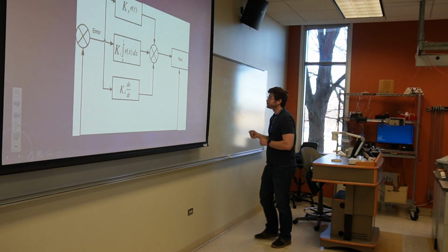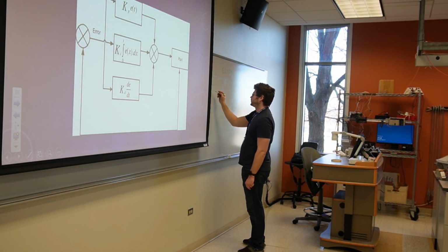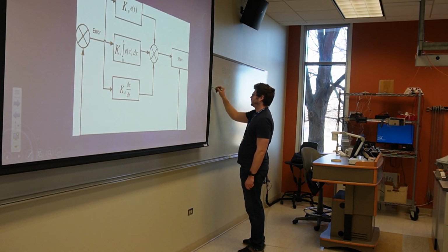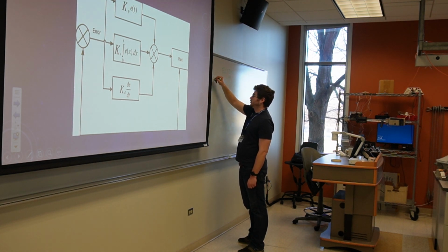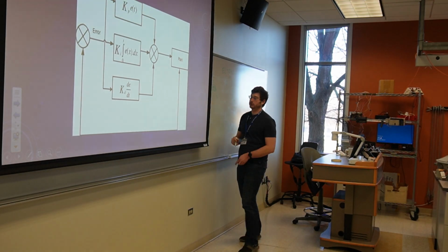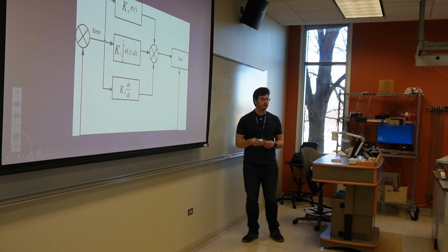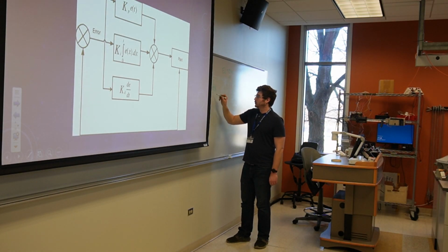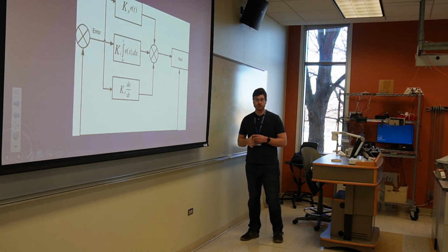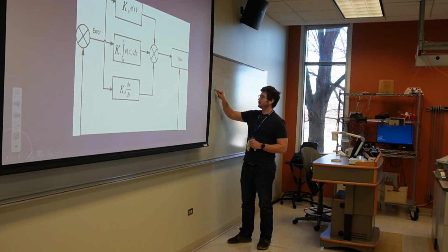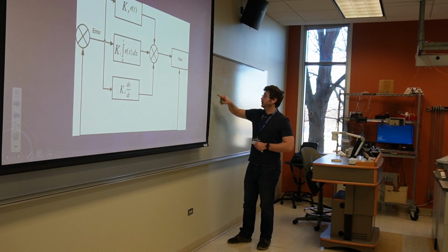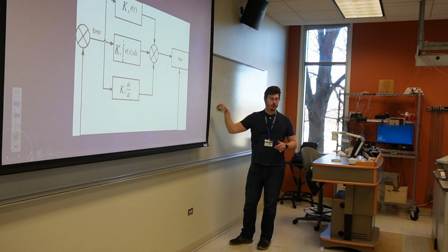So if you buy a little temperature controller box off of Amazon, it'll tell you what degrees it is, and you could set it up or down. Usually you'll have a little temperature probe on it, and it'll have a relay inside that you could attach to a heater of some sort, a silicone heater or a capsule heater, all that stuff that I told you about. This box is a PID controller, which is to say that all it really does is try to read the current temperature and get the output to drive that heater as hard and as fast as it can without overshooting, without undershooting, all that stuff.